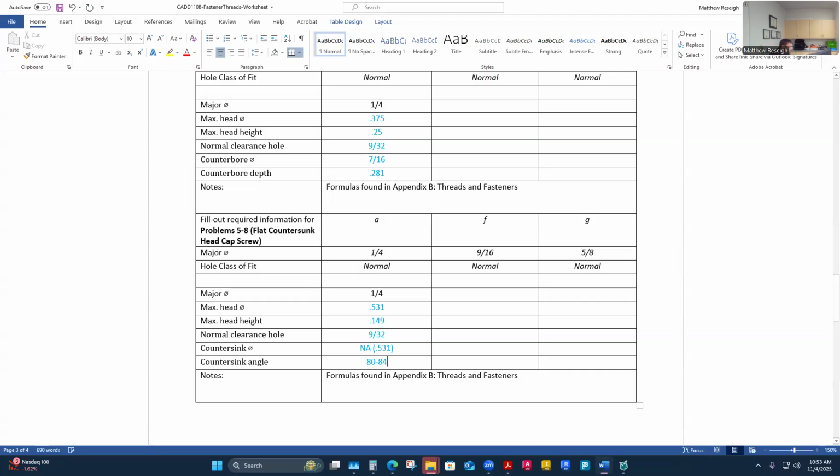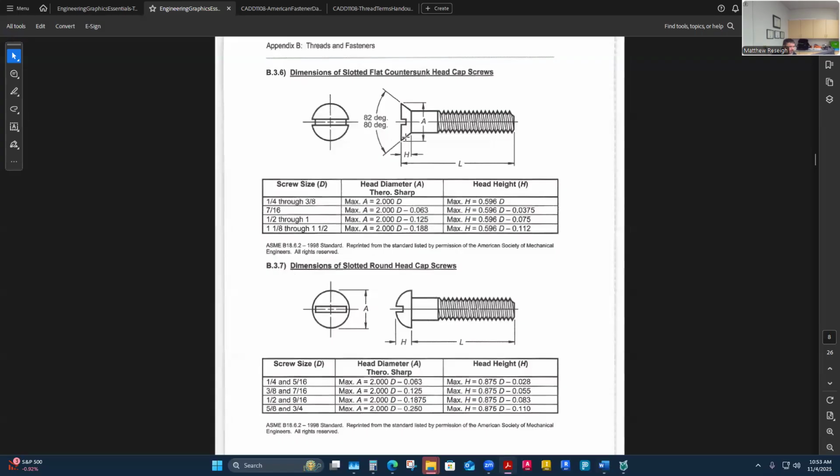I guess you could put degrees or whatever, but something like that. Then it's 80 to 84 degrees. Machine screws do come in different degree increments of how they mate to their counterpart, because when that fastener goes into its material, this is what's contacting and holding the load in some way. That is the mating surface of the countersunk material that it's going into. I don't know if we totally draw that relationship. The only one we really draw is a hex head bolt down through two parts. But yes, that 82 degrees is a mating surface.